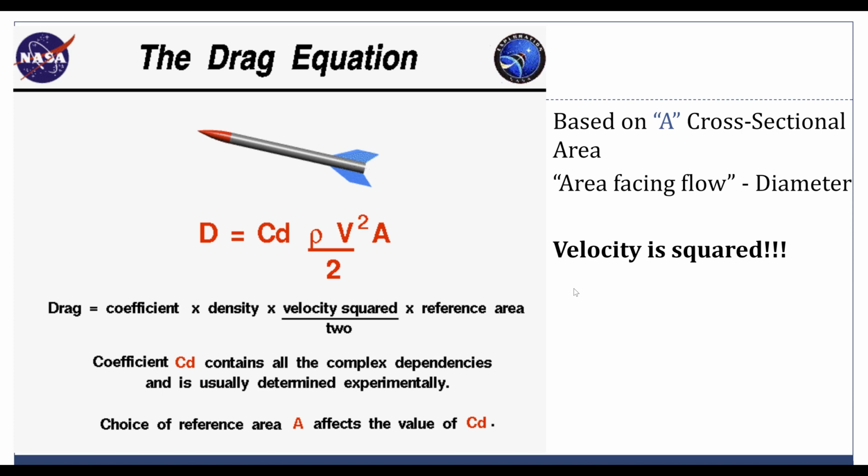So it's going to be a large difference in drag, and it's going to slow it down a lot. Same thing with velocity. The faster you go, the more drag you're producing, the less efficient your flight is going to be. The other thing to consider is the actual fluid it's flowing through. So if it's flying through air, for example, that's going to be a lot different than if you're flying through honey. So that's where the density rho comes in, right here. That's there as well. And the CD, which is going to be largely dependent on the shape. So I talk about that here.